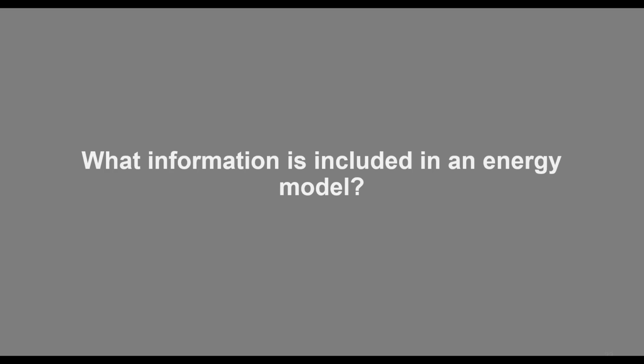I'd say it depends. Sometimes people are using heating and cooling load calcs just to do equipment sizing. That is a little bit different approach, although a lot of software and a lot of companies are now combining and doing their load calcs and their energy modeling at the same time. So it really does depend on what your aim is, right? An energy model is looking at annual whole building performance, whereas your cooling load is likely only looking at your 3 to 4 month peaks to get equipment sizing. So all right, we will continue to move on.